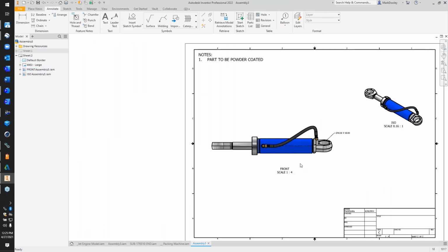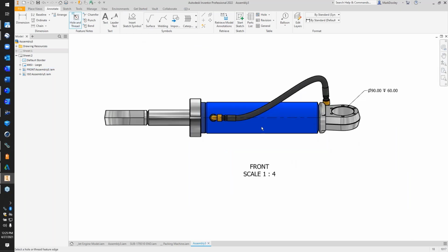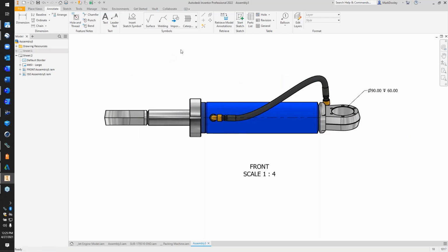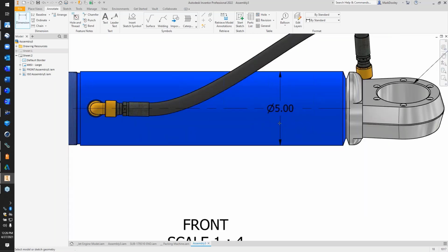So if we have a drawing, let's come over here. Here is one of my drawings, and we put a dimension. We don't need a whole note. We'll throw a dimension on there, and say I grab a dimension right here, and there's my center line right behind it. If I place a dimension on top of this center line, the center line breaks around the text. It has never done that before. It's been a pet peeve of a lot of users going, hey, why does this not break? It now does.